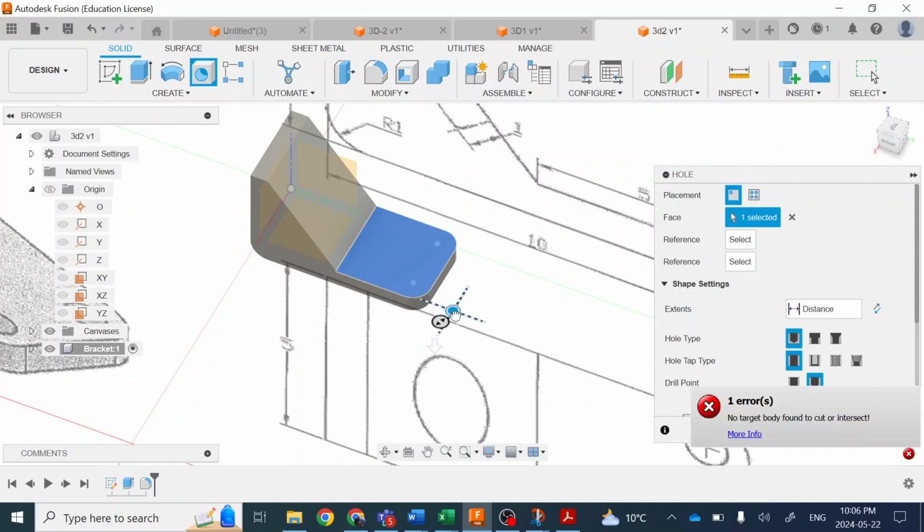Now notice very faintly you see a couple points that are highlighted, and that happens to be where my hole is going to go, on the same center point of my radius of the fillet I just added. So it's going to want to default there. It's going to want to snap to that point, which is perfect.